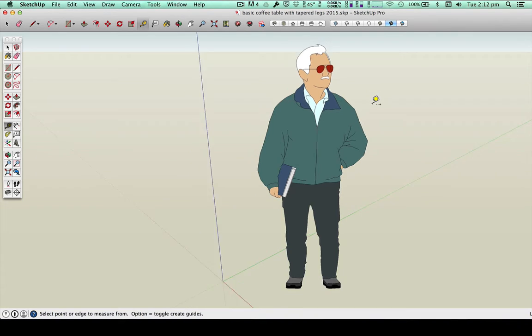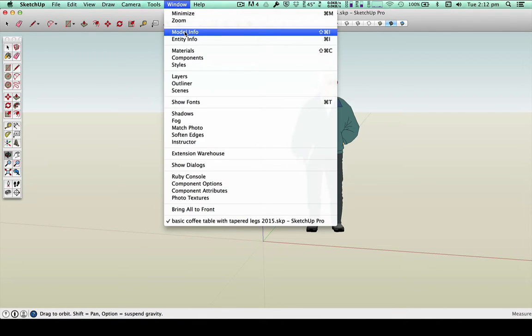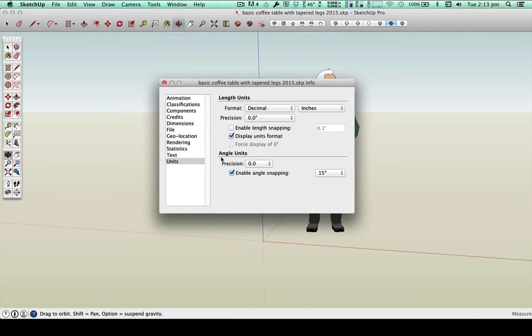In starting the drawing, the other thing I would do, I normally prefer, of course, being in Australia, they would always be drawn in metric. So the first thing we might do is go to Window, Model Info and check this for every drawing. Obviously you want millimetres for most drawings. Precision, I leave it at 1/10 of a millimetre. That allows me to do half millimetres, which is useful if I've got a timber like 19 millimetres. To draw a half of that, it's 8.5 millimetres, and that's why I leave it at 0.0 on the units.